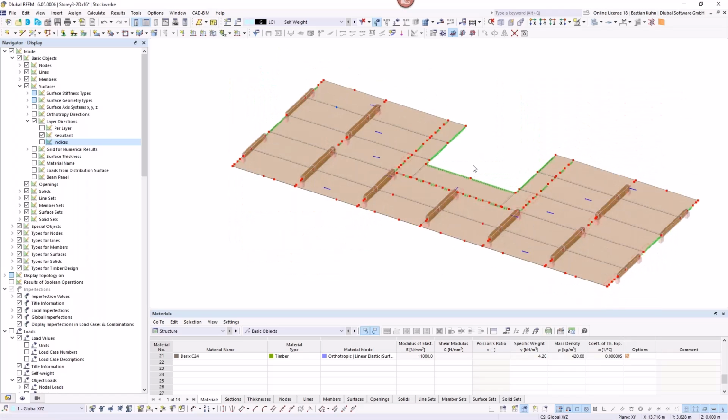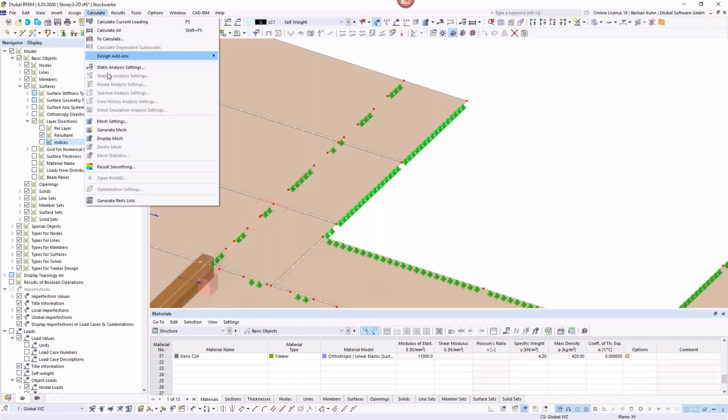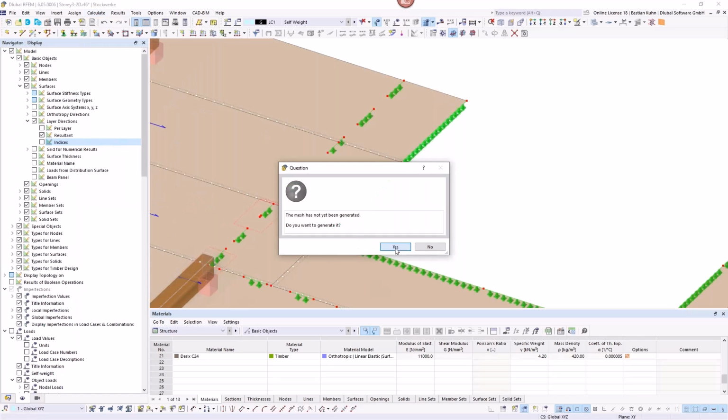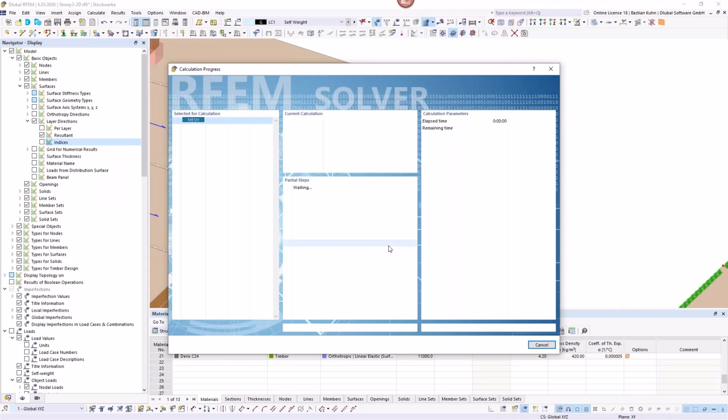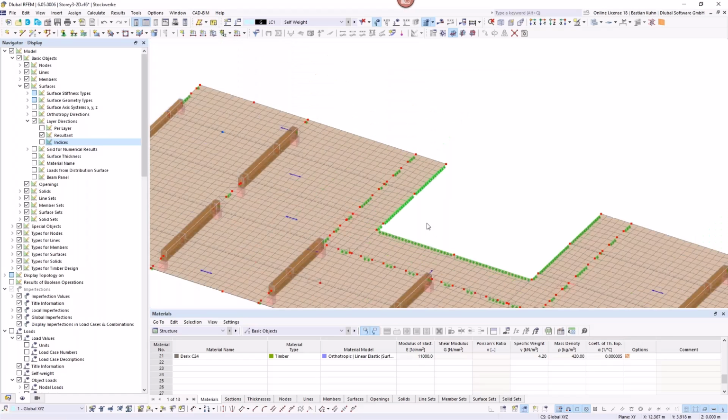All right, that is the plates. I also defined supports, just simplified, also only vertical and not movable in X and Y direction, because as we are only looking for vertical forces and deformation, I think this is okay. I will generate the mesh just to show you another part of what I made in this model.